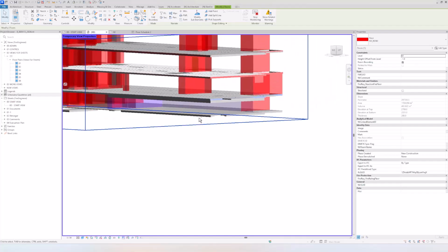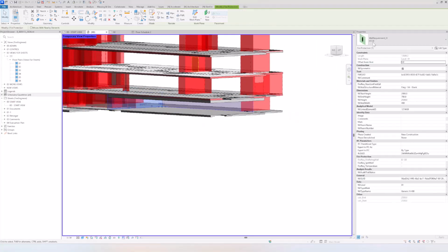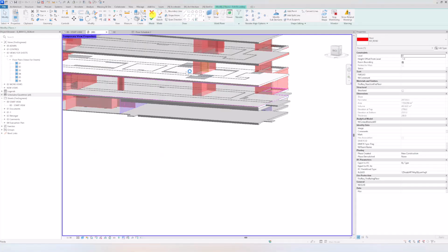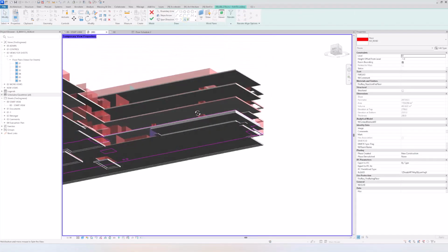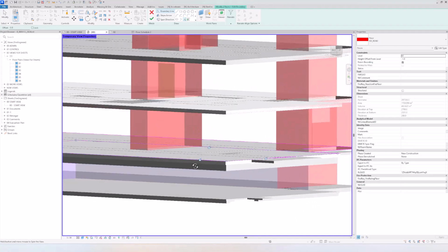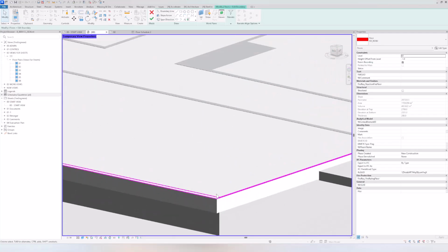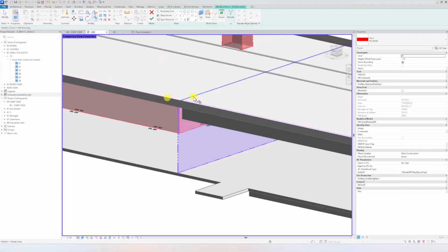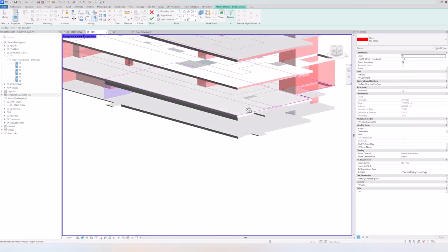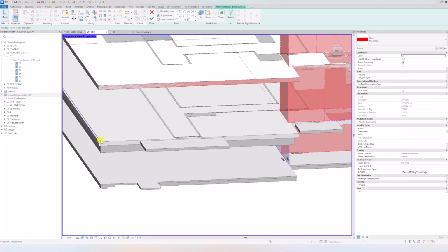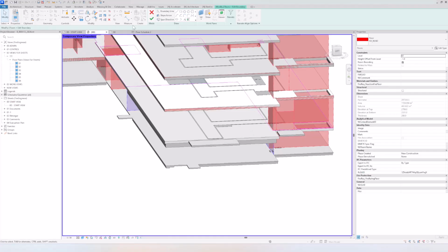So we can go down here, like this one should be a high requirement here. It should be 2 hours. So we can go with this floor, edit boundary, pick lines, go on the very bottom and just tab and select this slab. And we got the new one. So what I do is I usually just trim, take away as much as possible of this one. Go here to here. And you can delete a few things and go like that.